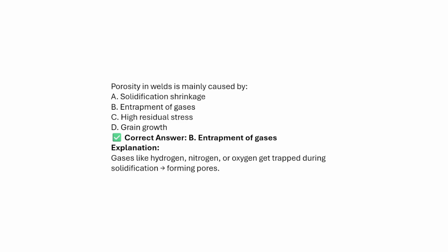Porosity in welds is mainly caused by: solution shrinkage, entrapment of gases, high residual stresses, or grain growth. The answer will be B, the entrapment of gases. Gases like hydrogen, nitrogen and oxygen get entrapped during solidification and form the porosities, pores.